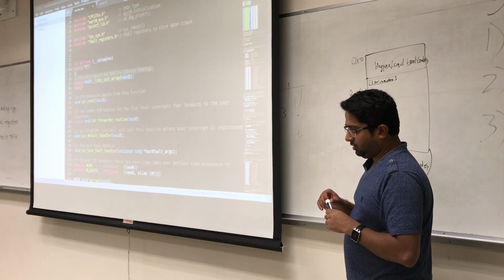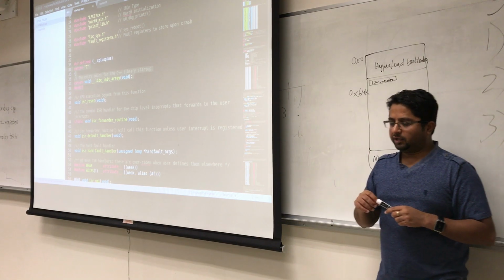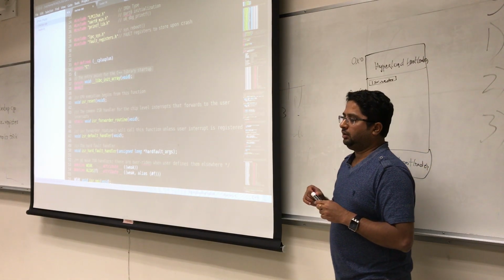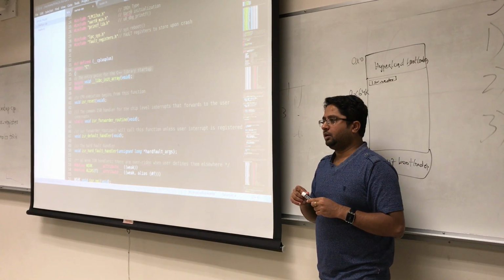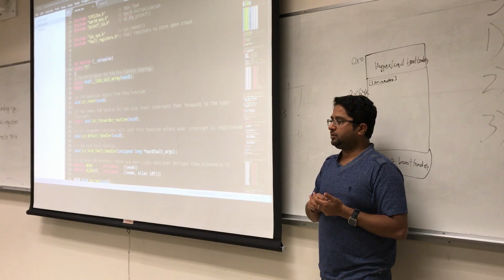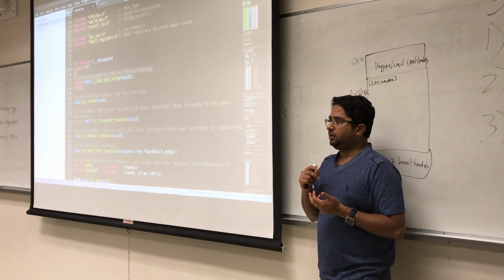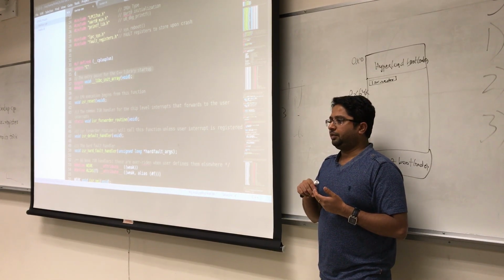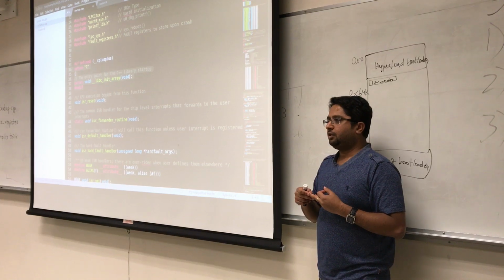Basically, what the implementation in that file does is it looks at a function handler, and it takes one of the pins. It takes a function as one of the arguments, and it takes what type of interrupt we are trying to handle.